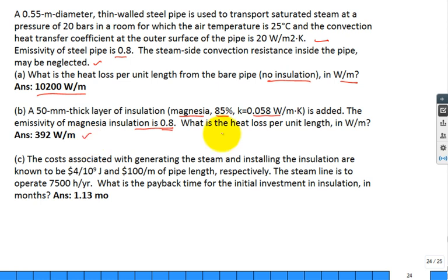Okay, so what you're going to have is, let me try and draw it like this. I have Q conduction that'll go out to the temperature of the outside surface of the insulation. And from there, it can be transferred, in an energy balance for this node, by radiation or convection to the surrounding.